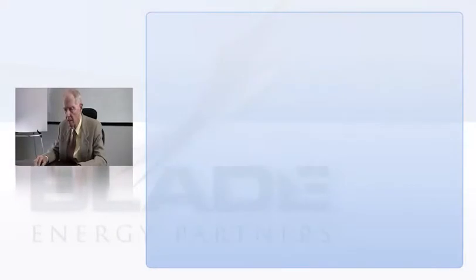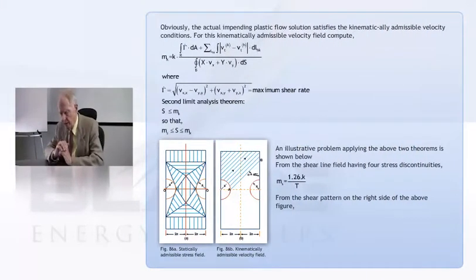You calculate this thing that looks pretty complicated but really isn't. It's this M sub k, and what it is, if you look carefully at that, is the work done if everything was yielding all over the place, divided by, well, I call it the internal work, divided by the external work.